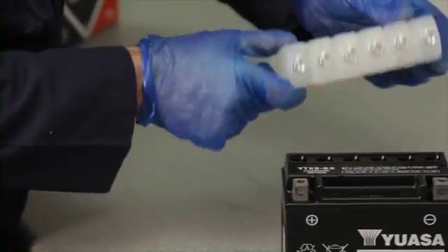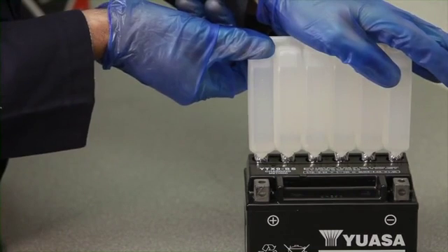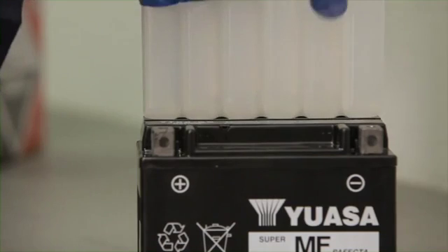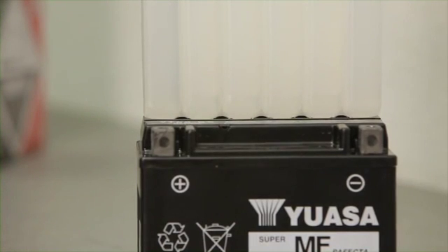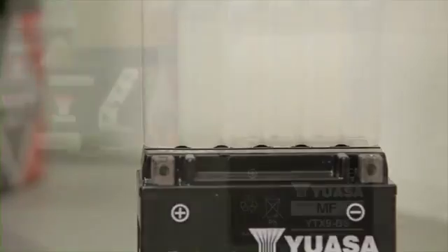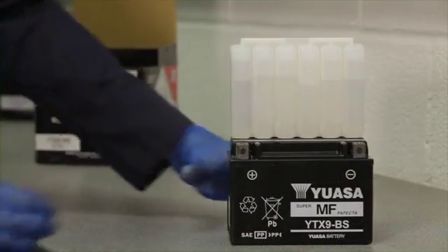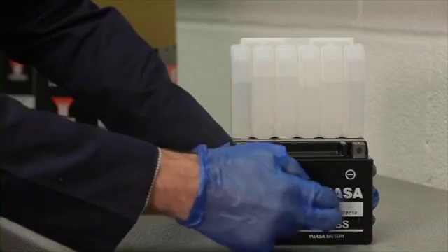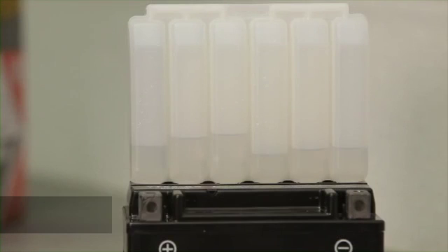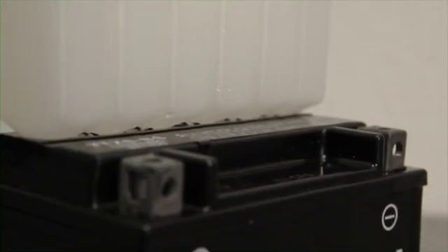The electrolyte container is made up of individual cells, each sealed at the top. Place it upside down into the filler ports of the battery. Ensure it's level and push it down to break the seals on the cells. Air bubbles should be rising in each of the cells, indicating that the electrolyte is flowing into the battery. If there are no bubbles, tap the container a few times, being careful not to tilt or squeeze it, as this may cause the cells to fill unevenly. Keep the container in place for a minimum of 20 minutes. Once empty, carefully remove the container and let the battery sit for 1 hour.